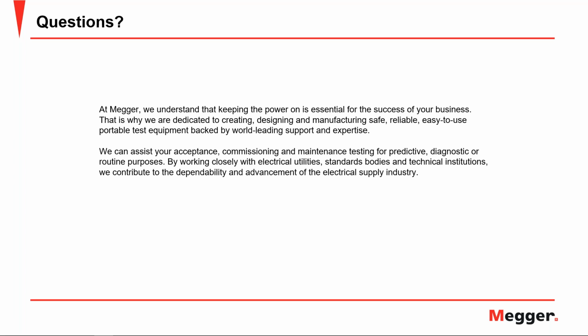Okay, good morning, everyone. This is a good question to emphasize a point that Daniel brought up in his presentation when he was talking about the ground fault pickup testing. When he talked about that test, he said that it's preferred to do the pulse method. So basically, you want to sneak up on it as you increase your current level and apply it to the device until it trips. And this 90 to 125% tolerance for that value comes from the NETA standard that Daniel referenced for both the acceptance testing standards and the maintenance testing standards.